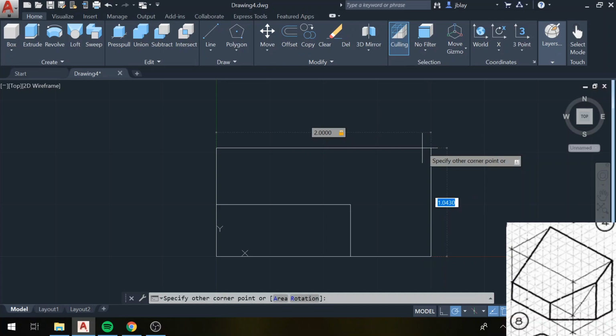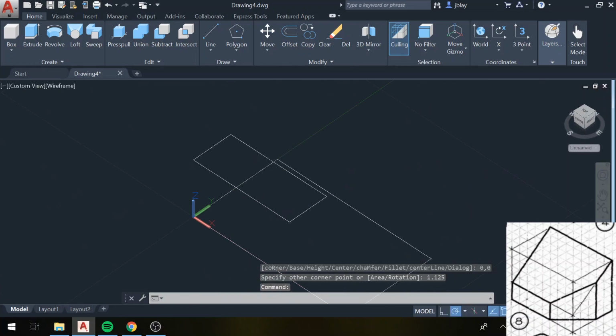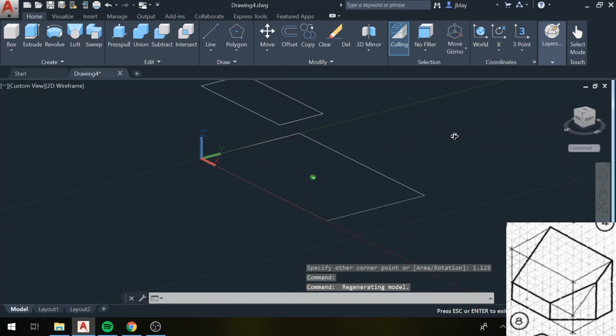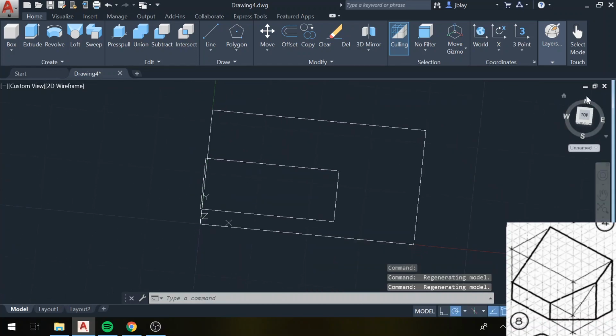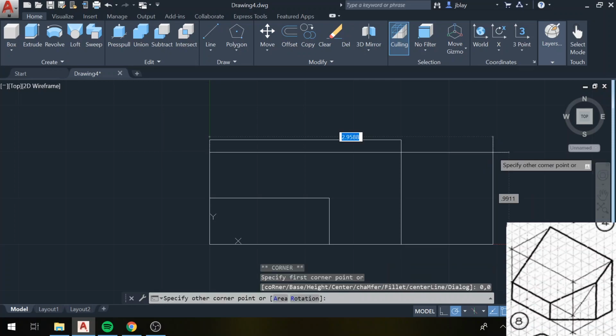And then my height is going to be 1, 2, 3, 4. If you look closely, it looks like there's half a block there, so it's 4.5 blocks, which is going to be 1.125 inches. And I'll just rotate to make sure that these look right. They do. Good. And then I will draw another rectangle, started at 0, 0.